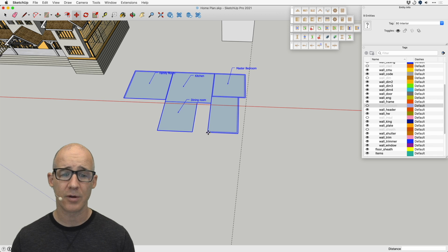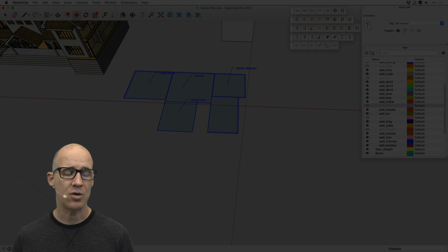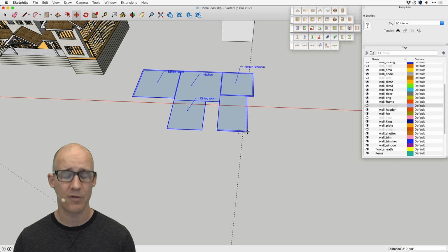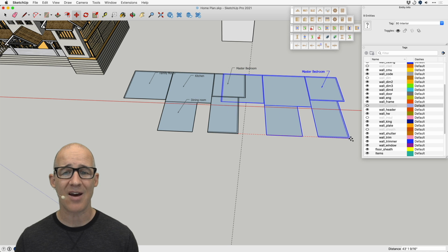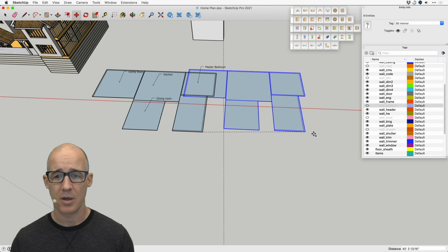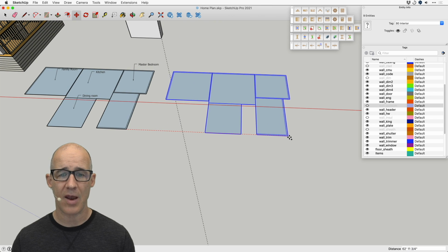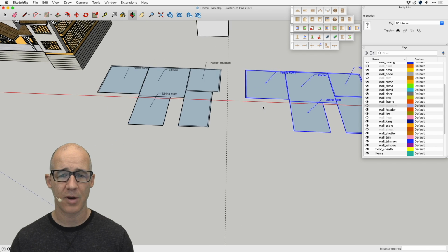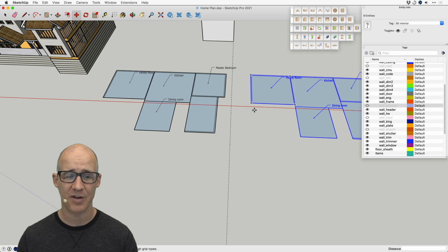I'm going to hit the M tool to move. I'm going to click a point to drag, and you can see down at the very bottom, I believe I'm covering it actually. It's down here underneath me, but you can read whatever a tool is going to tell you to do. In this case, on the Macintosh here, I can option. So in this move, I can start to move, but if I hit the option key, it's going to make a copy of all of this. And I'm going to drag this. Again, that pan tool, the first video I ever shot about being able to move while you're working with tools, that is so critically important, being able to pan with that middle mouse button and the shift key.